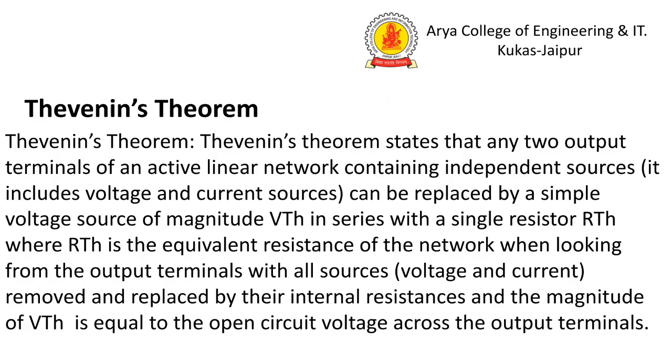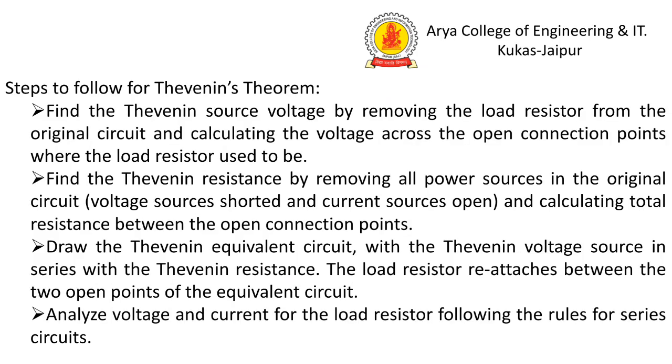Rth is the equivalent resistance of the network when looking from the output terminal with all sources removed and replaced by their internal resistance, and the magnitude of Vth is equal to the open circuit voltage across the output terminal.